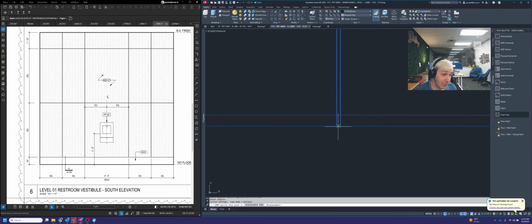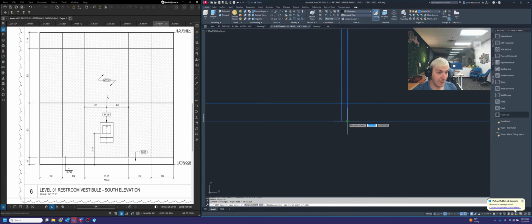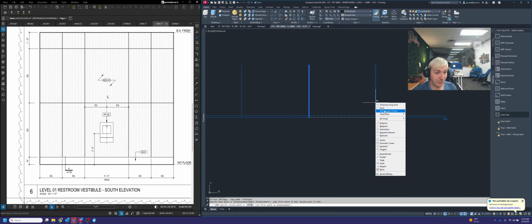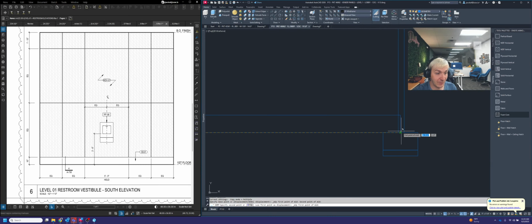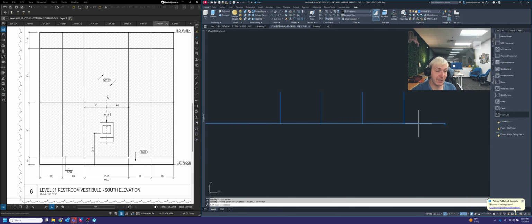And I want the middle of this 1/4 inch. So I don't have a snap point for that right now. So what I need to do is hold down Shift, right click my mouse, and go to mid between 2 points to get there. I'm going to go from this corner to this corner, and then hold down Shift and right click one more time. And I'm going to snap to this corner to this corner here. Let's just verify and make sure that we have 2 equal panels now at this point. So it's DIST, we're checking that. So that panel is 30.20314. This panel is 30.20314.